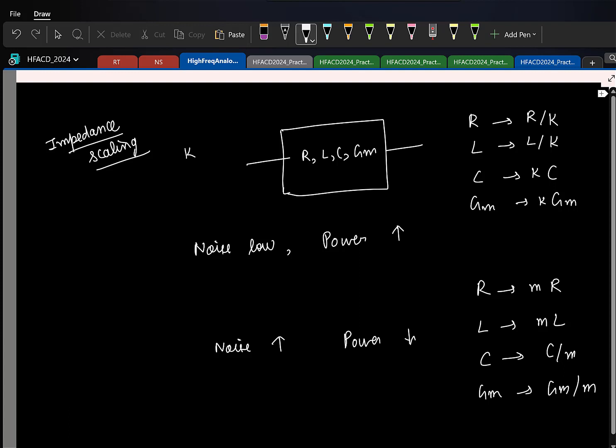Generally, now let us say you want to characterize your op amp, or some analog circuit, with respect to noise and power. If I only look at the noise, that is not a great metric, because the brute force way to reduce noise is to increase the power. Similarly, if I look at only the power, I can arbitrarily reduce the power by having higher noise. So what would be a metric to look at?